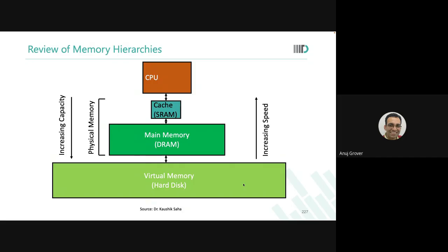Because of these packaging technologies, we are able to scale the memory performance tremendously. Not because memory intrinsically has improved, just because now you don't need to go to the PCB. You can directly transfer information from one die to another just by placing them one over the other, through silicon vias, or so many ways in which we are now able to connect multiple dies on the same chip.